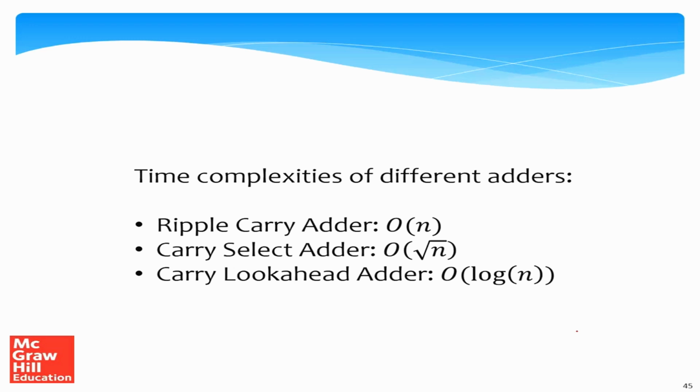So what was the idea of the ripple carry adder once again? The idea of the ripple carry adder was that we basically have these fixed size blocks, and maybe with 1 bit pair or 2 bit pairs, doesn't matter, and then we do the addition and the carry sort of ripples. So that's the reason in the worst case it can take order of n time.